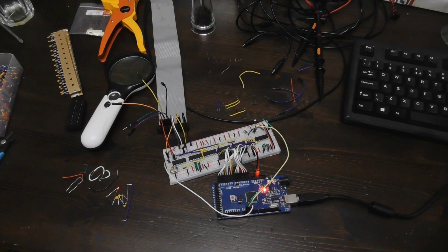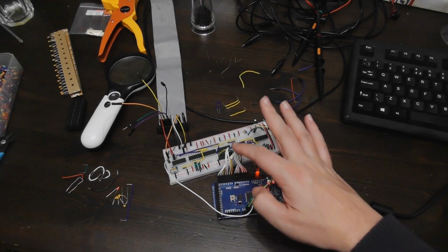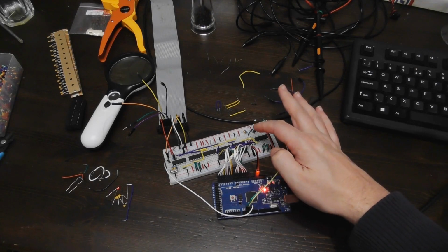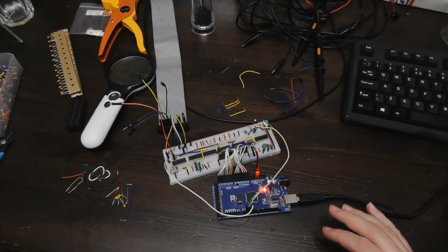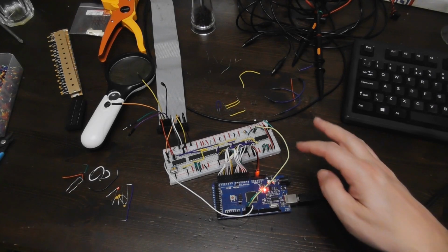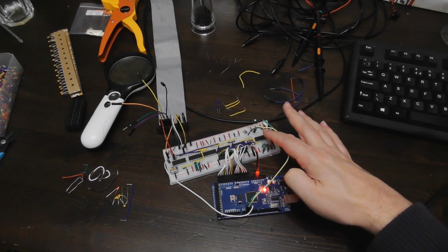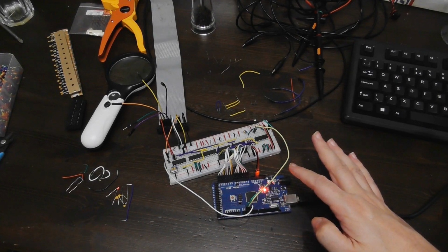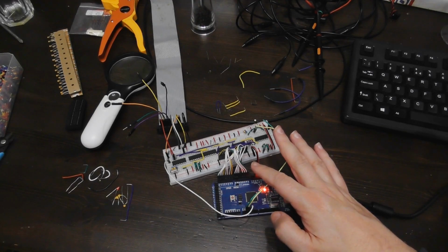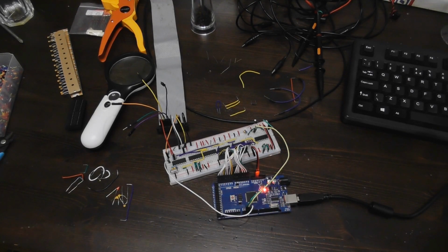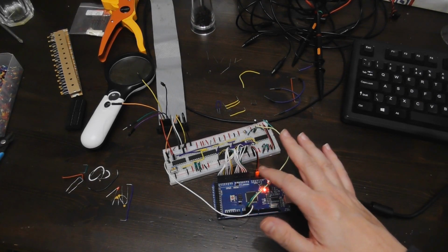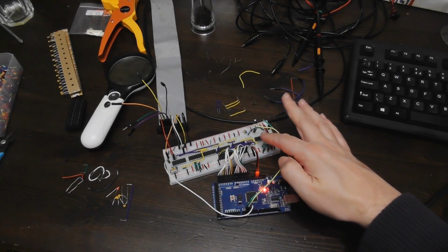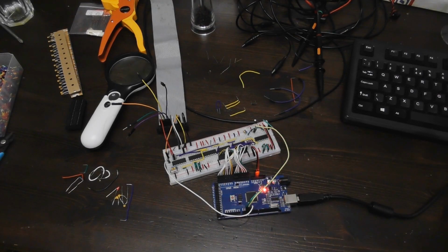One thing that I haven't done yet here, that will make life even easier for the Arduino, is latching the actual bytes coming from the shift registers when that clock pulse goes positive there. The reason that would be a good thing to do is that currently the Arduino is only notified once every 64 microseconds by that byte signal. But it still has to read the shift registers really quickly before they've moved another bit. So there's still a kind of a timing constraint there that I'd like to get rid of. And simply putting some D flip-flop latches after the shift registers, which are triggered by the byte signal here, would probably do the trick for that.